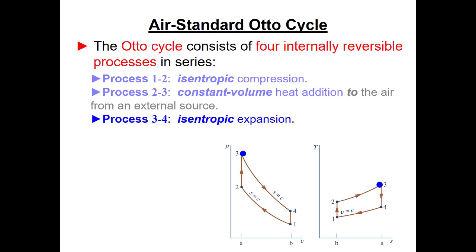Next, we're going to have the isentropic expansion, right? This is the whole reason that we're running the internal combustion engine. This is sort of equivalent to now we're burning the fuel in the cylinder, the gas is expanding, and it's pushing that cylinder down. So as the cylinder gets pushed down, we increase the volume and we drop the pressure, right? This is doing work on the piston.